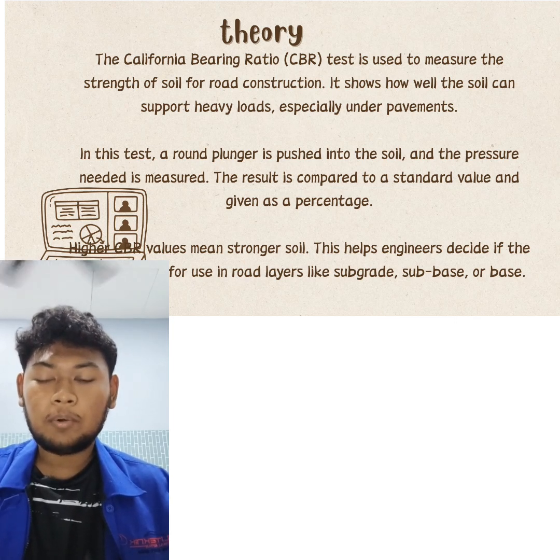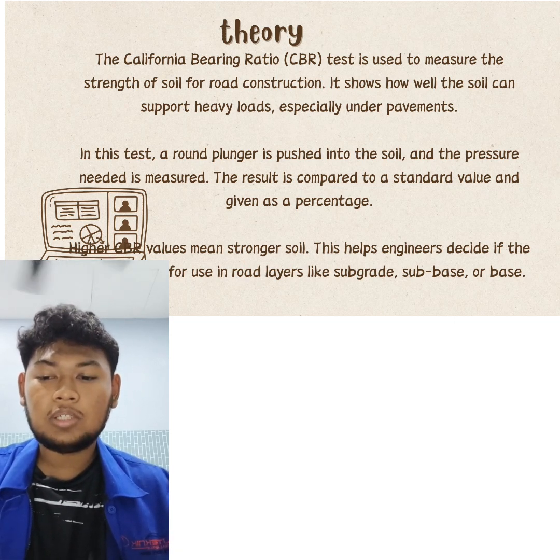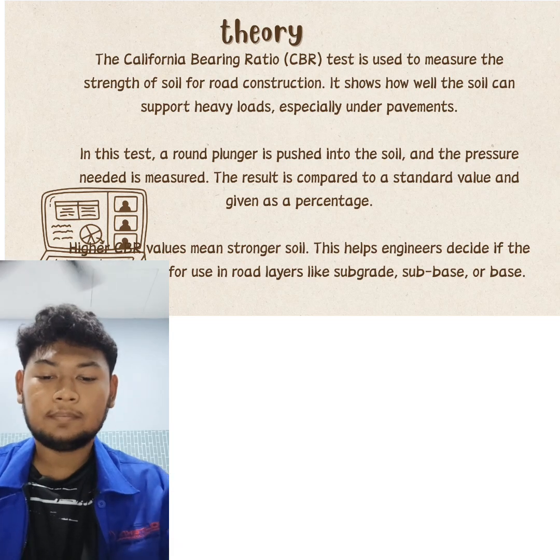This load is expressed as a percentage of the standard load value at a respective deformation level to obtain the CBR value. Table 4.1 below gives the standard loads adopted for different penetrations for the standard material with a CBR value of 100%.